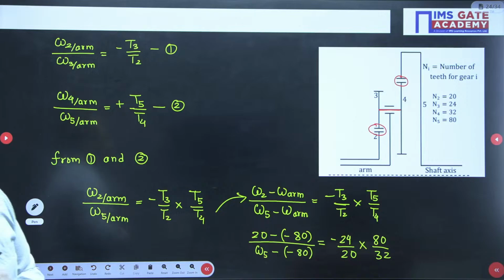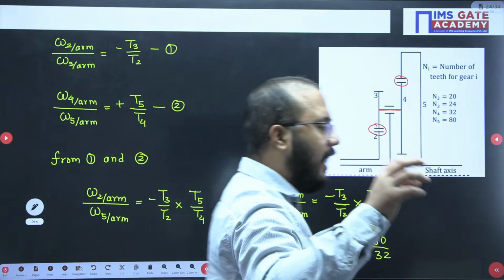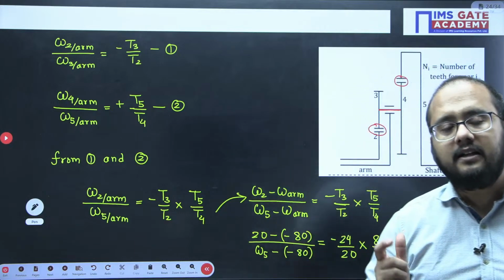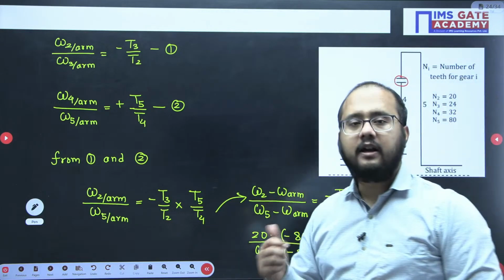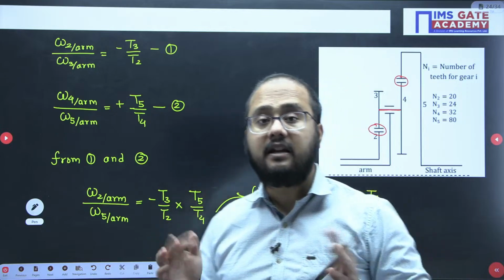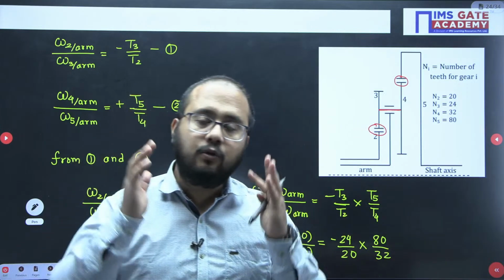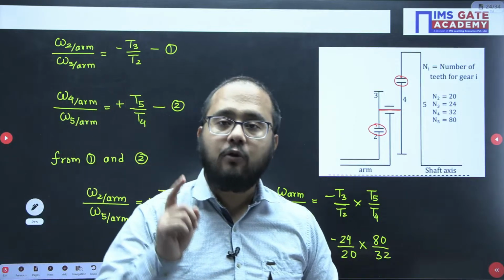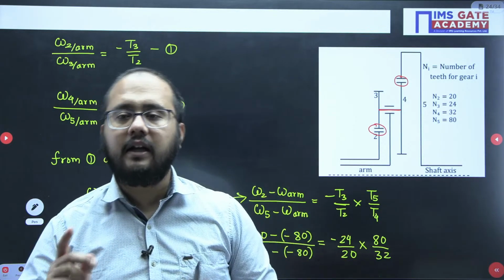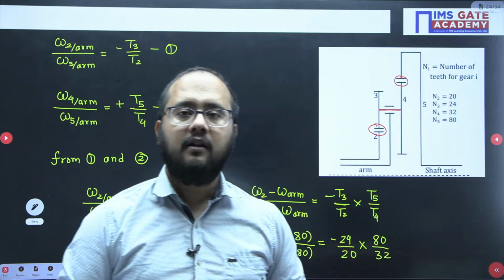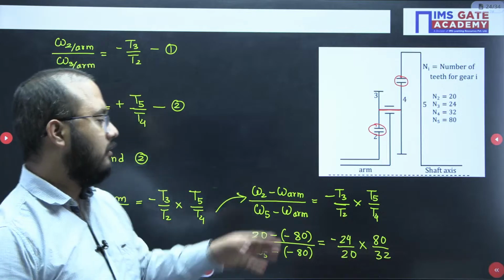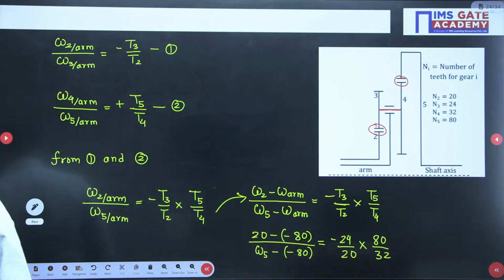Line diagram questions are also easy, but you have to understand how the gears are meshing, whether it is internal meshing or external meshing, or whether the gears are compound gears. So you have to closely observe the gear train given in the line diagram. How to draw an external gear and an internal gear is the required part in order to understand any line diagram. Now you can easily solve it and tell me your answers.